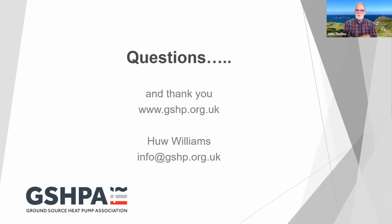The first question is from Duncan Ray. He would just like to know approximately what the distance was between the injection and abstraction boreholes in that model playback that you showed to us. Oh, that being a theoretical site, I think I just assumed it was a fairly typical office block in London. So I think I had about 50 meters in that case.